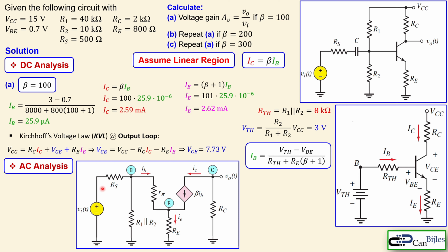This is the small signal model of this circuit, and specifically the dashed part here in red is that of the transistor, the BJT, and this is the most basic, most simple model. You see here a dynamic resistor, R pi, we will use that shortly, and we see here a dependent current source, and it's called beta times IB. Everything is here in the AC parameters, so there are small letters and small subscripts. This base current here will be multiplied by a beta, which is the exact same beta as we have here, and that will then produce here an AC collector current. This part is again only the transistor.